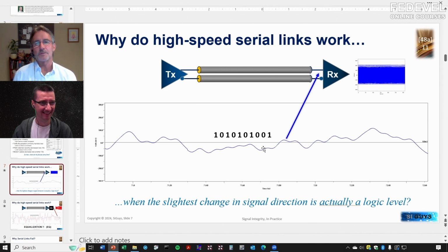What I think is important to communicate is the very slightest nuance, the slightest change in even slope. If you read my PCIe Gen 5 paper, there are even more extreme examples. Just the slightest wiggle of the waveform or change in slope indicates a different logic level. If I wrap this waveform into an eye diagram, there is no signal. There is no eye. There is no open eye, right?